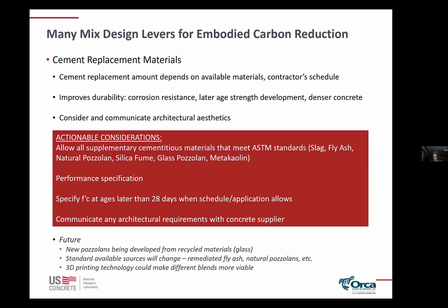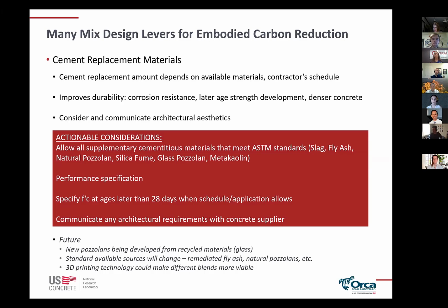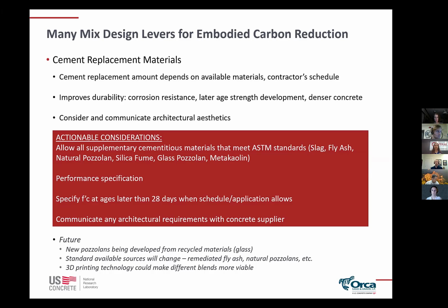Then additionally, as we continue to go into the future, the standard available sources are probably going to be changing. Fly ash comes from burning coal, and so as some of those sources of power start to change, you're not going to have fly ash as readily available. And so there could be other things that may be coming out on the market. There are fly ashes that have been put into landfills that could be remediated and used in concrete. We may be looking more at natural blends as sources. And so just as the market dynamics change, we may be looking at different sorts of supplementary cementitious materials in the future.